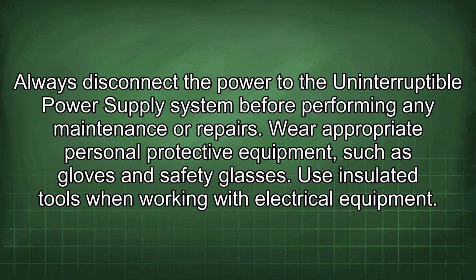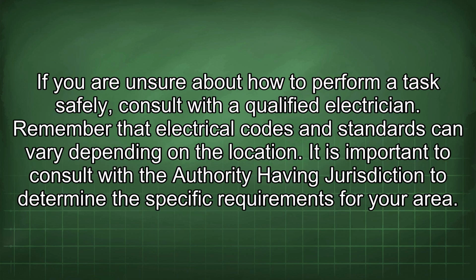Always disconnect the power to the uninterruptible power supply system before performing any maintenance or repairs. Wear appropriate personal protective equipment, such as gloves and safety glasses. Use insulated tools when working with electrical equipment. If you are unsure about how to perform a task safely, consult with a qualified electrician.